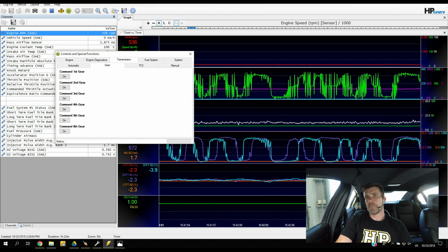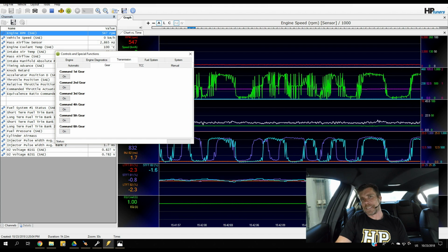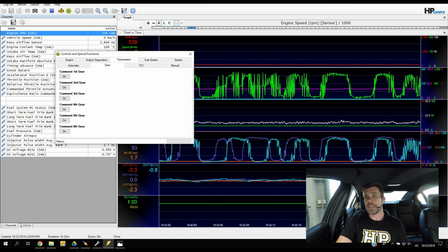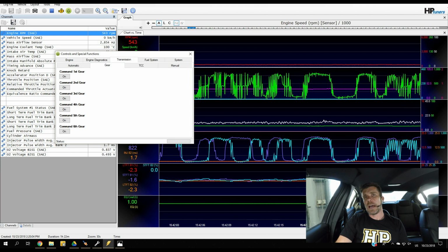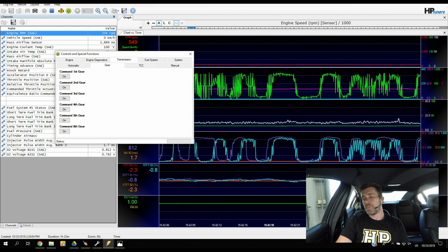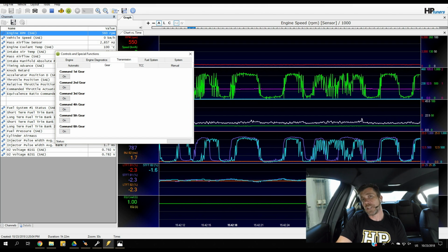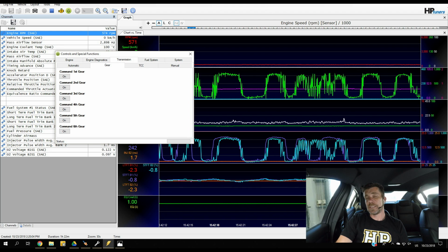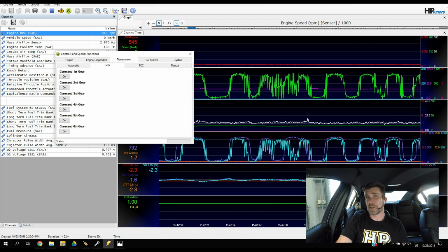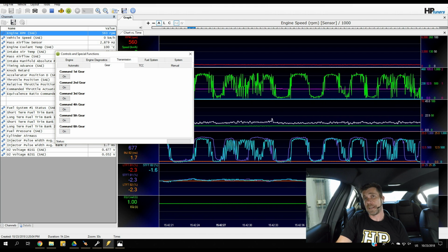You might get to something like about 80% throttle or thereabouts. Now, obviously it's not ideal, you aren't at 100% throttle, but bear with me because this is a technique that does work really well. Then the point is you're going to start your ramp run, and you'll be able to find that almost as soon as you start performing that ramp run, you can start to gradually increase your throttle opening. And again, depending on the particular application, you might find that by the time you're at around 2800 RPM, maybe 3000 RPM, you'll be able to smoothly go to full throttle without it kicking down.